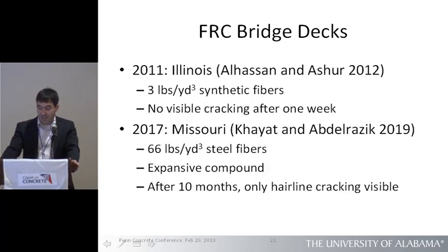In Illinois, there's a project with 3 pounds per cubic yard of synthetic fibers, and no visible cracking after 1 week. This study was more looking at plastic shrinkage cracking, early age cracking of bridge decks, and in this study, they successfully mitigated those.